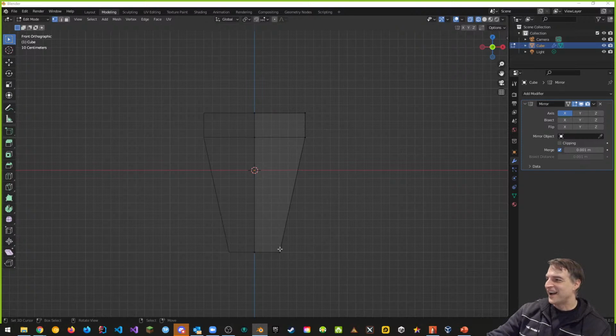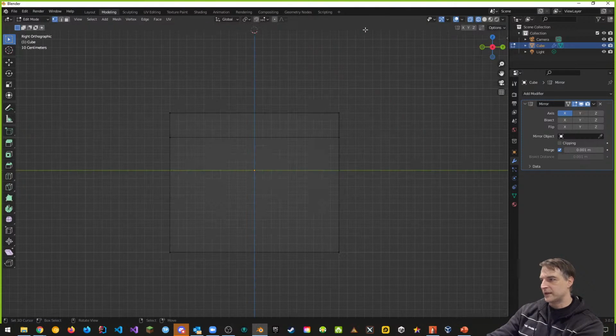Hotkeys are hot, yeah. So this is the first piece. And what I want to do now is go to the right side. So I want to switch to the right view by clicking the 3 button on the numeric keypad. In Blender, you click, press the 3 key, and you're at the side. Notice that this is clearly not correct. I moved my 3-dimensional cursor around, but that's okay because I can move it back to the world origin, no problem. So does that make sense?